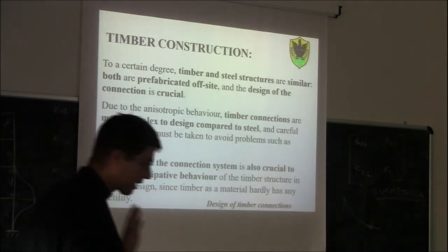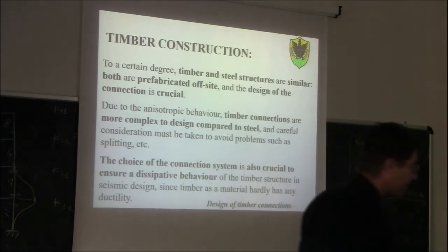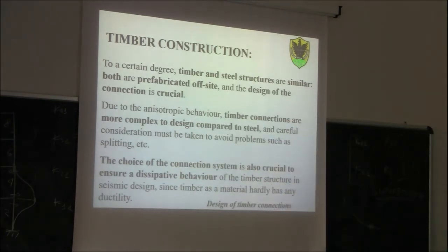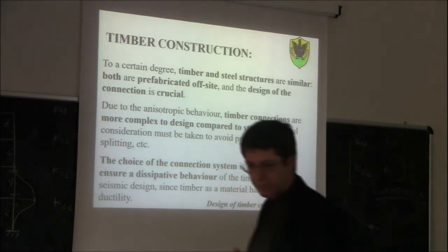So for timber structure, since timber is an inherently brittle material, we will be able to get some ductility, some energy dissipation only in the connection system. So only by designing properly the connections to make sure that the metal fasteners are going to plasticize. Okay?